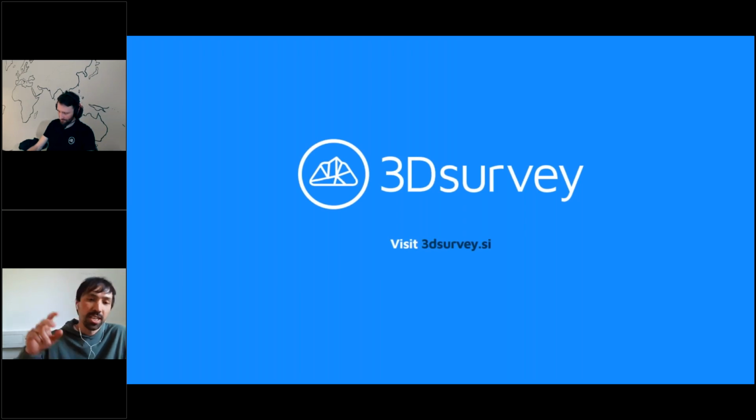You just use the right mouse click on the mesh. There is an option, convert mesh to point cloud, and you will be able to say, okay, give me 1000 points per square meter, and in this way you will create a point cloud from the mesh and calculate the profile lines. So this is a workaround. Maybe for the next one, yes. So we see there are more tips and tricks available. So thank you for your question.